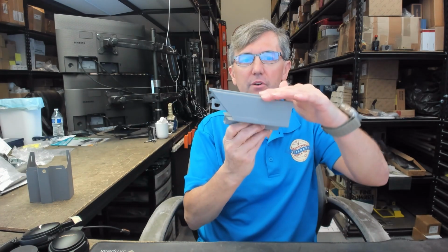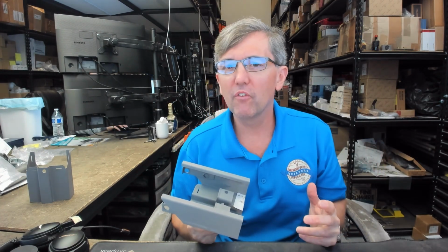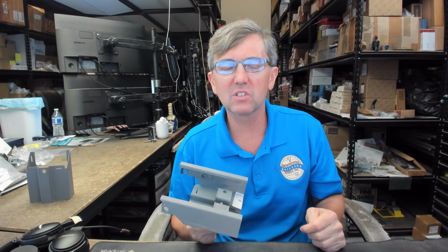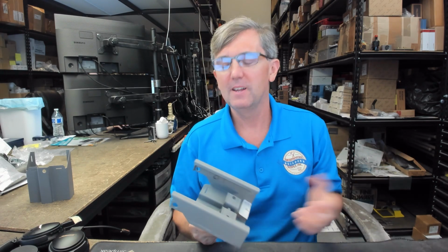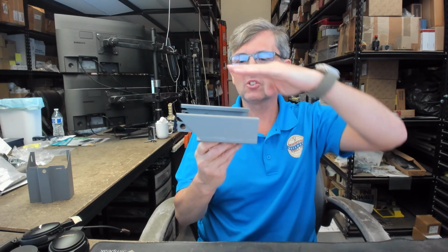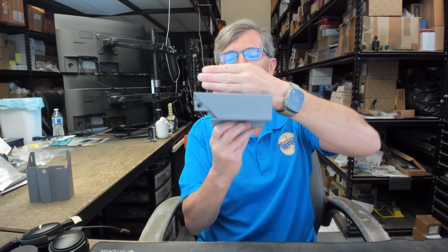If someone's not asking what rough opening size they should leave, you can count on sooner or later people calling and saying, yeah, what's wrong with your frame? What do you mean what's wrong with my frame? Well, I can see the underside of the stud from the header. And well, what rough opening did you leave? Well, I left 39 by 86 1/4. And I say, that's not the size that is in the email. That stud's got to come down so the header can go up and over it.